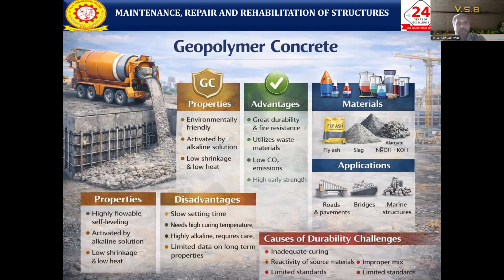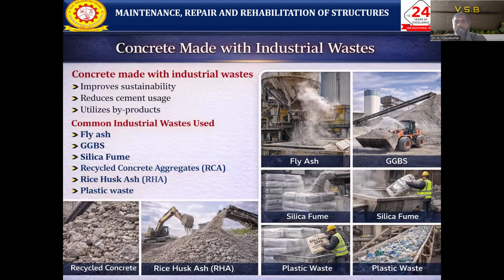Okay, the properties: high flow and self-leveling, activated by the alkaline solution, low shrinkage and low heat. As for disadvantages: slow setting time, high curing temperature needed, high alkalinity requiring care, and limited data on long-term properties. We can use geopolymer concrete for roads, pavements, bridges and marine structures.